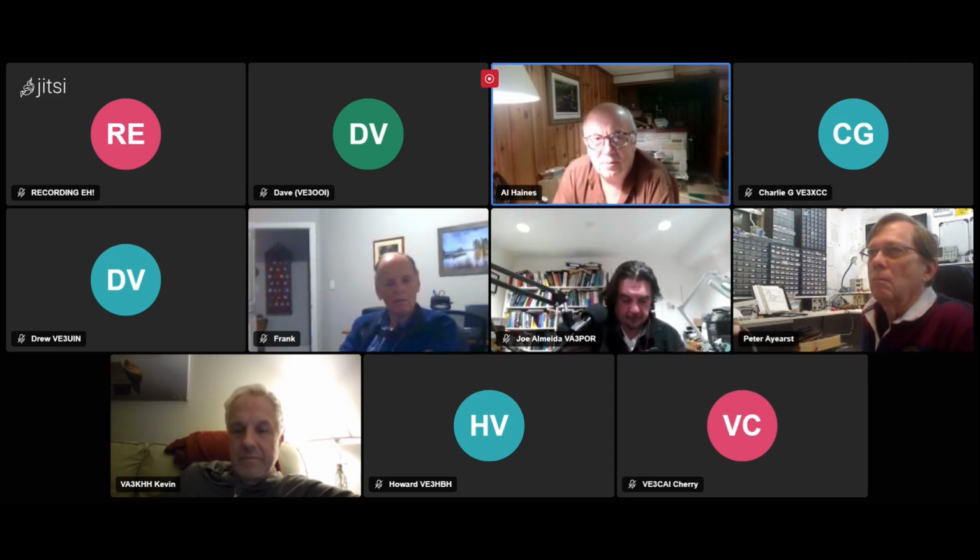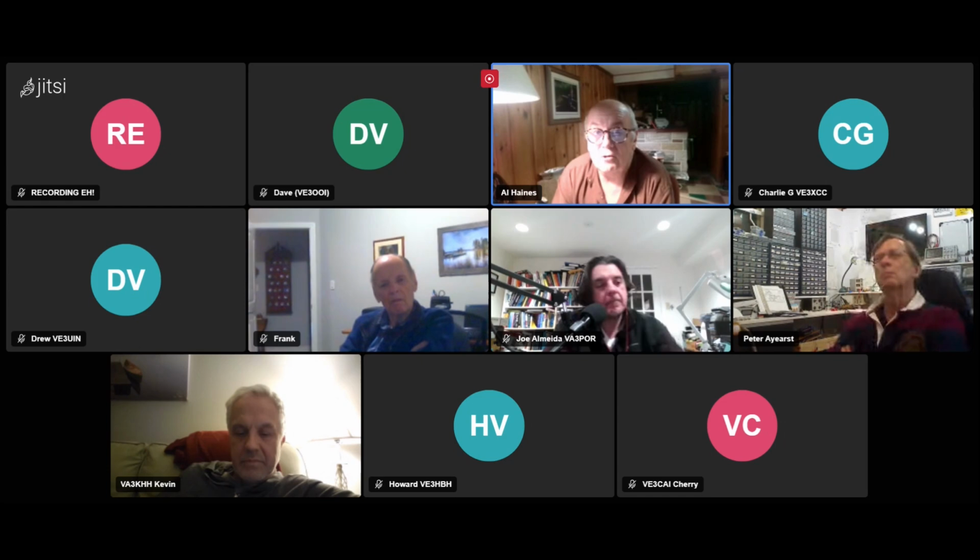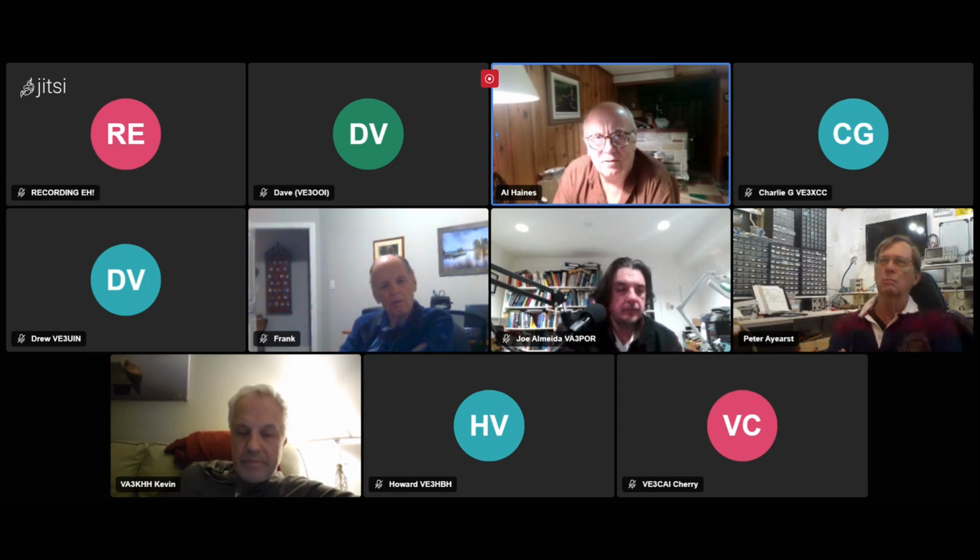A couple of things I noticed: for an extra $200 or $300, you can get your resolution bandwidth down to 1 hertz rather than 10 hertz. Doesn't sound like a bad thing to go for. The other thing I was wondering is the ultimate frequency range on this.